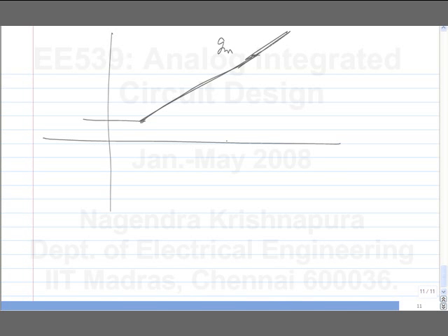And the part through the other branch, the passive branch, is like this. So this is due to GM and this is due to CGS and RS. And the net impedance is the parallel combination of the two. On a Bode plot, you can approximate the parallel combination by the smaller of the impedances. So you will get something like this.